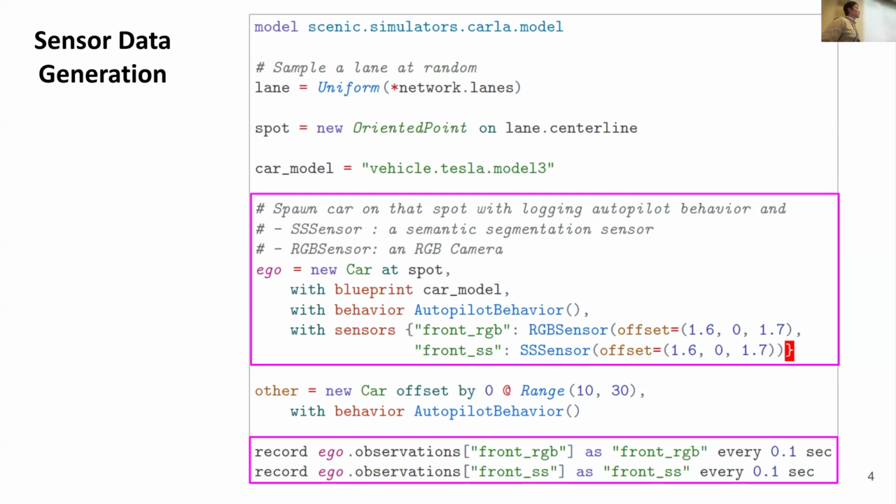I'm just wondering, if I sample one frame per second but out of sync, can that be a different distribution? You might need to define a least count where you can actually capture those discrepancies. So you need some information about the sampling rates of the different sensors and then compute the time interval to sample, which is typically a fraction of the individual sampling rates.